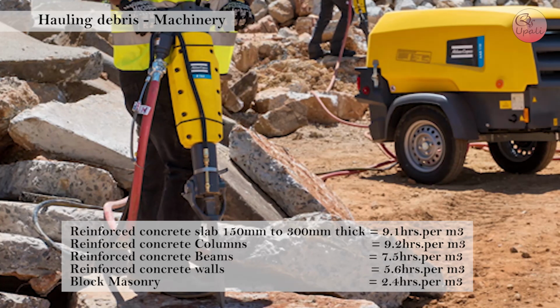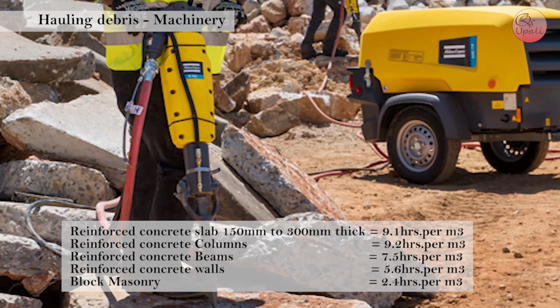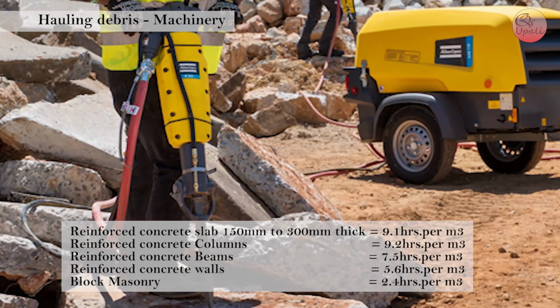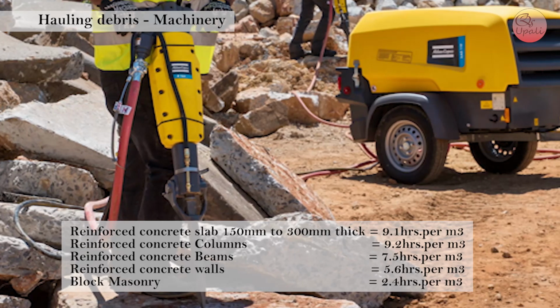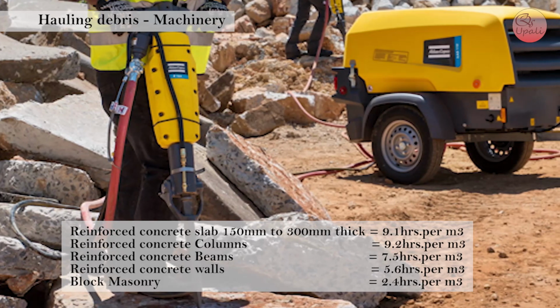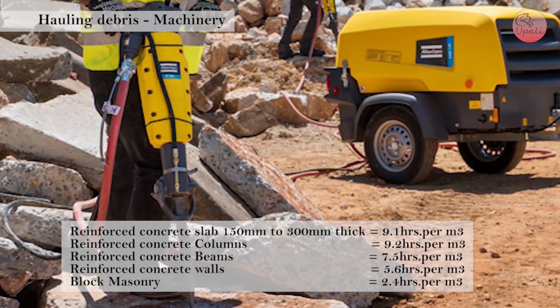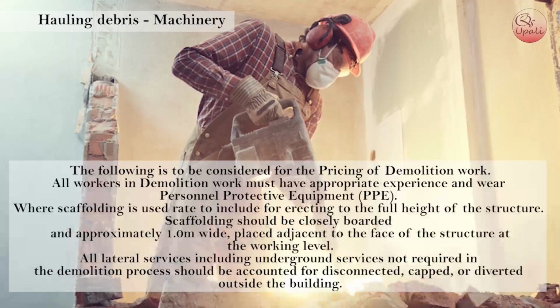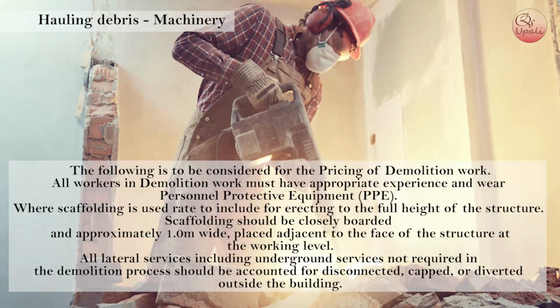Reinforced concrete columns 9 hours per 1 cubic meter. Reinforced concrete beams 3.7 hours per 1 cubic meter. Reinforced concrete walls 5.6 hours per 1 cubic meter. Block machinery 2.4 hours per 1 cubic meter. The following is to be considered for the pricing of demolition work.